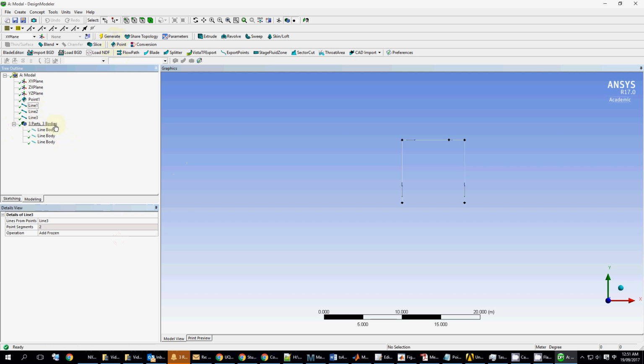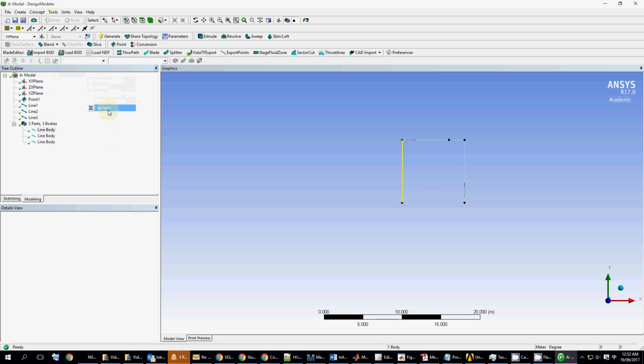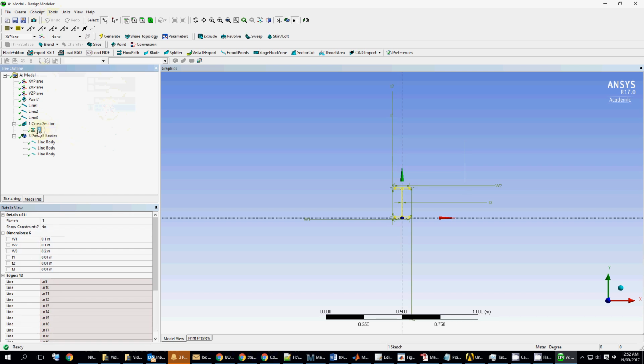Alright, so in that way we see we have created three lines, line 1, 2, 3, but it automatically creates three paths, which are line bodies 1, 2, 3. You can see they've been highlighted, but they need a cross section, which we haven't defined yet. So we want to define our cross section. So it's just Cross Section, I section. We can call this one top, for the top beams, and for these top beams, we just leave the defaults.